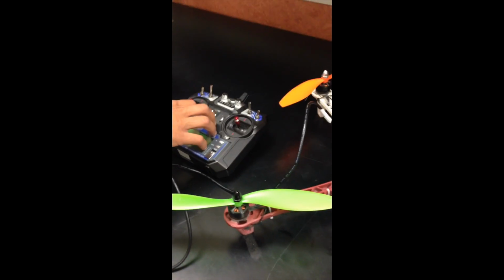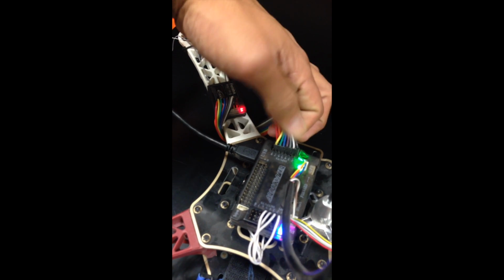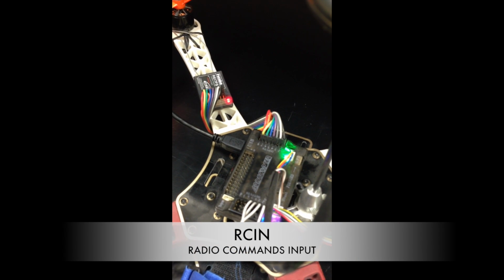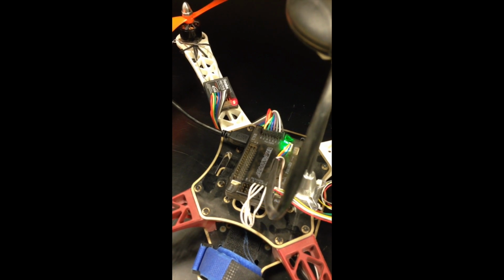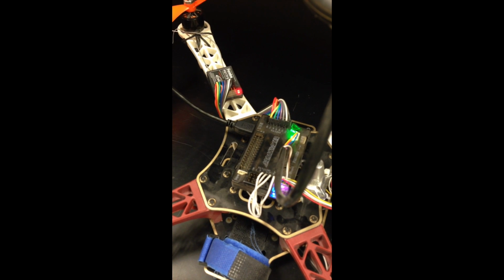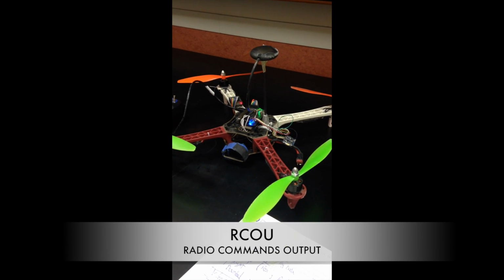We can see that we have the 4 degrees of freedom. This information is sent to the controller by some signals that are input, and this is called the radio input in the log analysis file. Then the signals are processed by the controller and an output signal is sent to the motor. In particular, we have 4, and it can control the angular velocity of each motor, and this is called the radio output in the log file.